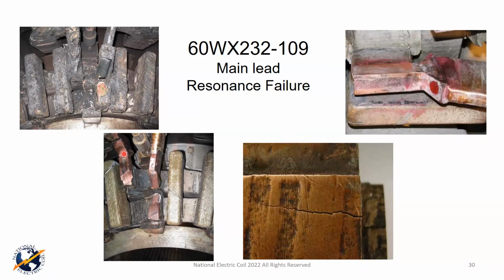And the geometries, you know, alone may or may not have led to cracking. You can see the sharp geometry on this one right here. We would rather have seen that in a nice sweep, which is the way we did it when we replaced these, by the way. But because of the resonance and the high vibration, we found stress cracks in many of the other connectors. They just hadn't failed yet, okay? And we proved it by the bump test first of the other connectors that weren't damaged, and then by stripping them and cleaning them and looking for it, and this is what you found, okay?